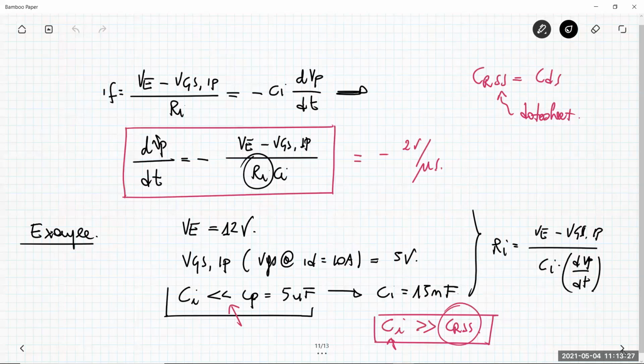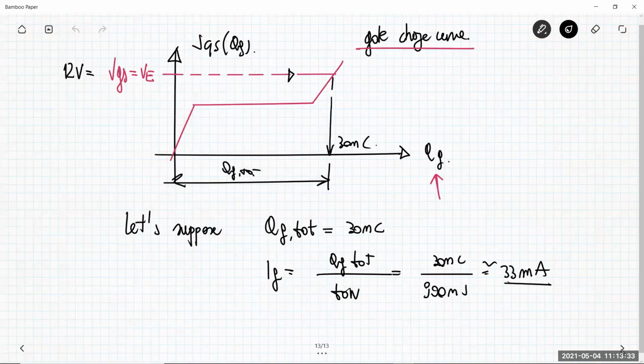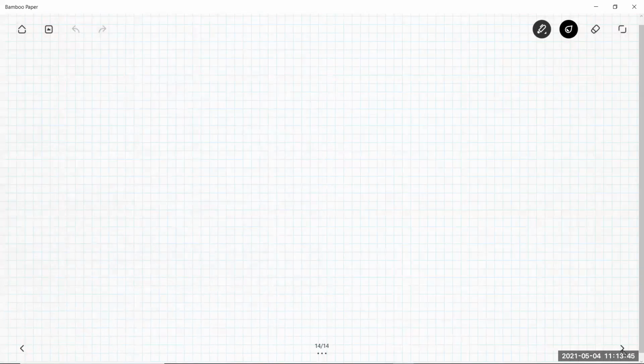During the turn on and off, the gate current is not null. The current through the MOSFET is null for static operation, but during the turn on and off you have to charge and discharge internal parasitic capacitances, and this is the need for this driver behavior.